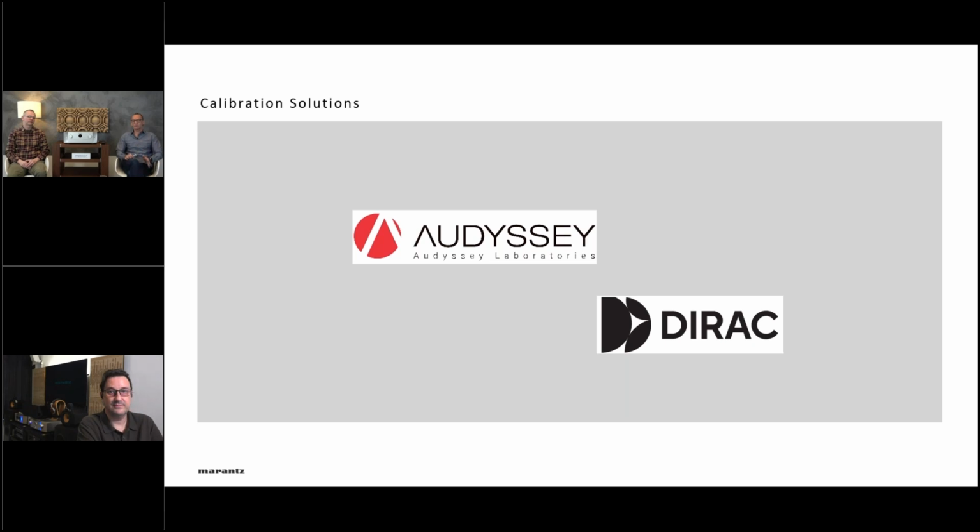Why do we need room calibration overall? No room is perfect, of course. We have reflections, we have some limitations in placing the speakers and so on. You're all aware of these kinds of limitations. Here, my first recommendation is to try to get your best possible setup before doing any calibration with these tools. See that you can place your speakers in a proper space. Try to move them slightly around.